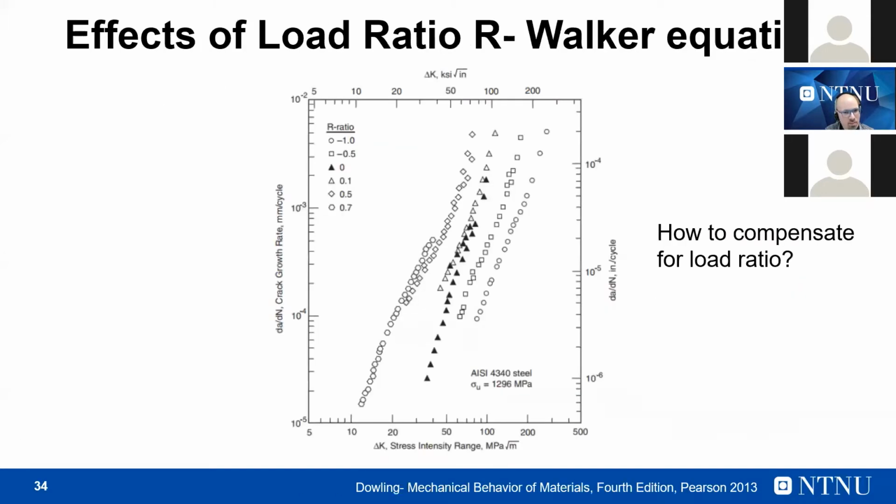And another important aspect, as I mentioned before, that I wanted to stress again, because if you have defects, this is very important. If you consider additively manufactured components, this is a key aspect. What we have to consider is the effect of the load ratio, and see that also in the Paris curve, this effect is very, very strong.